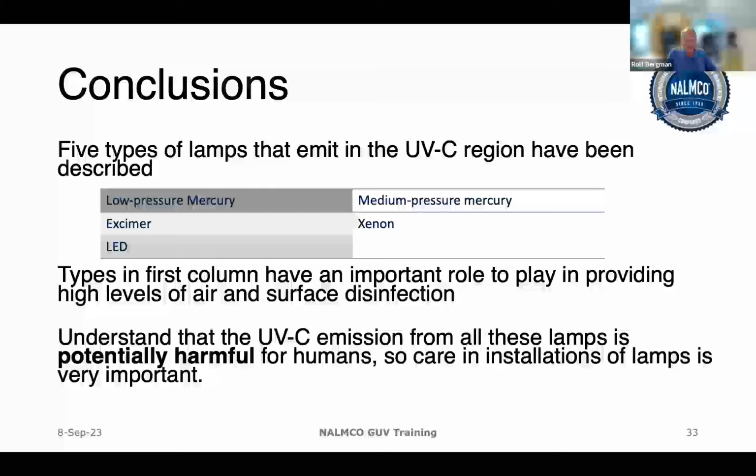You must understand too that all of these lamps, any emission in the UVC is harmful if applied above a certain amount, that is in radiance times time. We'll talk much about that in another lecture. So depending on the situation and whether people are present, how you install the lamps and how you maintain this system is very important. We say potentially harmful because in well-installed situations, they are not harmful. Thank you very much.